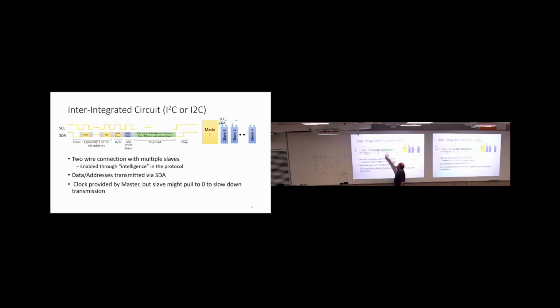Then I send whatever I want to write, and then I'm done. Yeah? That's one transmission. Takes longer, because there is a lot of overhead, this address and so on. Requires quite some logic to implement. Has the benefit for a virtually arbitrary number of slaves, we can use only 2 wires, 1 clock and one data wire.